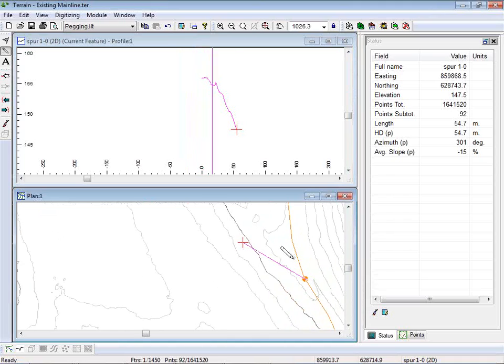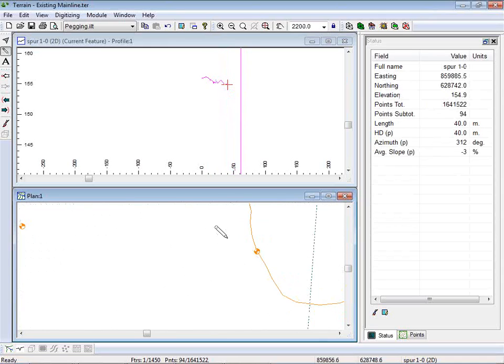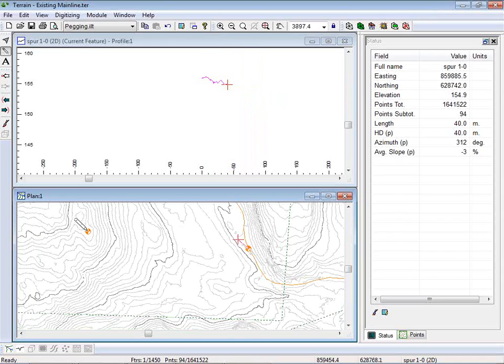Great. So, well, I'm branching off of a road here, and the grade on that road, by the way, is 3%, and we're starting to go downhill. So I better not go down too fast. We're going to have a strong grade break there. Let's say -3% for my first leg. I'm going to zoom back a little bit. Okay, we want to go up here. What if I just did that?